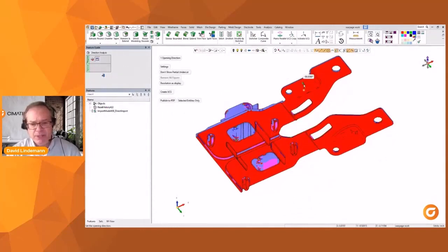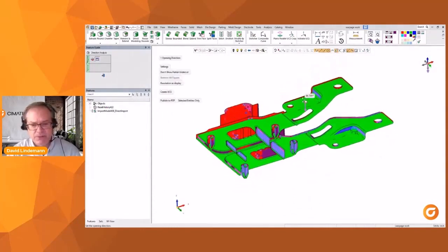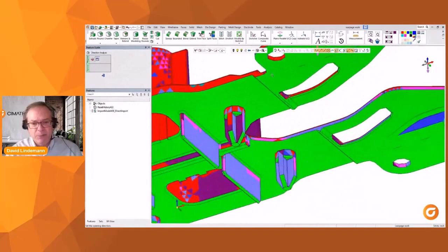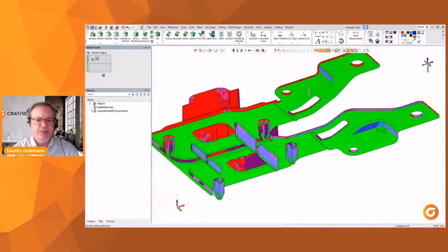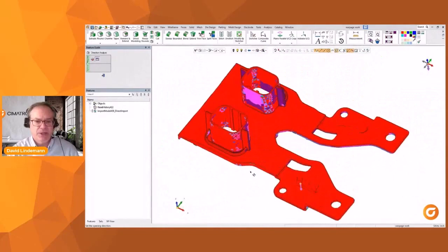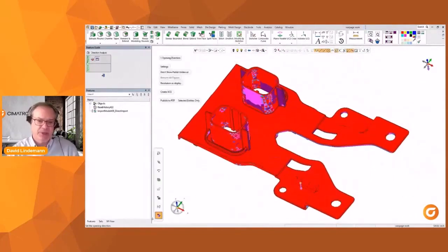And what you see, based on the range of colors and values, is anything in red in that pole direction, which is the pink arrow, that's undercut. So along these bosses that are sticking out the bottom, I've got about 2 degrees of undercut. Or I may see some undercut too, depending upon the pole direction along the side of the part.